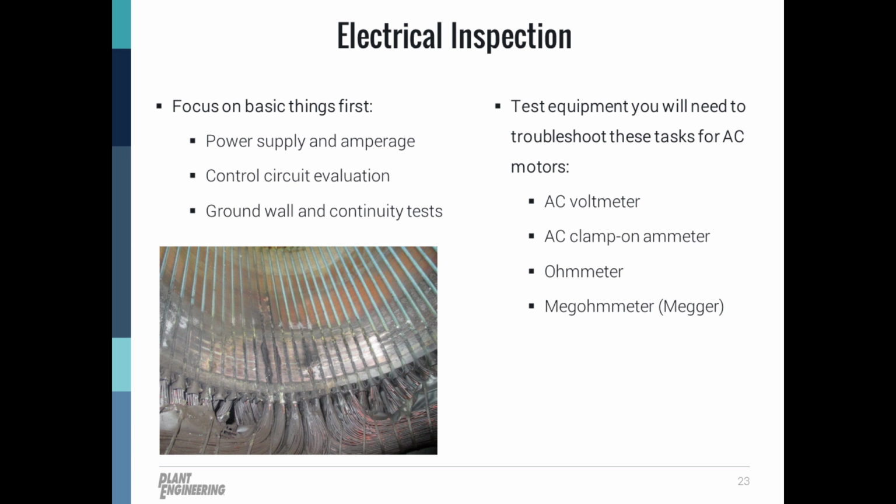So, the continuity test can be performed with an ohm meter. It should be tested from the leads coming directly from the start switch or VFD. By doing this, you can eliminate any possible broken power cables that may be running in conduit or underground. If the continuity test fails, disconnect the power cable at the motor and perform the test again between each phase of the motor to pinpoint if the failure is in the motor or in the power cables.